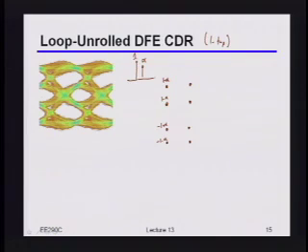If this is the previous bit and this is the current bit, which analog levels can I start from in the previous bit, and which analog levels can I end at in the current bit? And by the way, I'll give you a hint for a clock pattern. The previous bit is always different than the current bit. Where the signs are opposite?